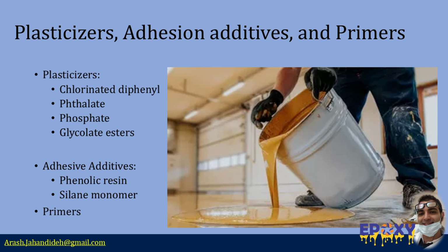While most building sealants already include adhesion additives, these alone may not suffice, especially on difficult substrates. For bare metals, a diluted sealant-based primer is often necessary to improve adhesion. For porous surfaces, a film-forming primer is applied to block moisture migration at the interface, which can compromise adhesion over time. Primers can also serve as barriers against gas permeation through the substrate.